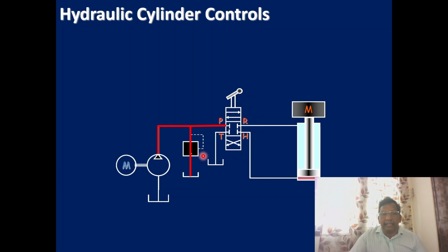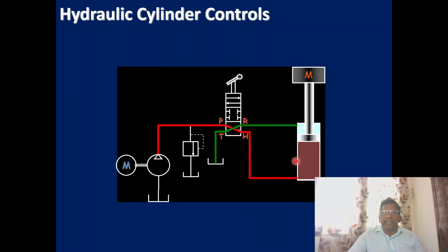In between, for all hydraulic systems, we need a pressure relief valve. Now when we are applying the force, it is moving. So what will happen? It moves the piston out. So it is carrying the weight. Okay. So when the pressure increases, the cracking pressure setting is exceeded, immediately it opens